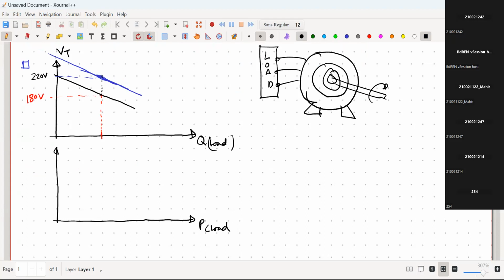Why? If there is a real load connected with the generator, there will be current flowing through it, and this current will produce an RMF, which will try to oppose the rotation of this rotor. So if I do not increase the diesel supply or the force in the shaft, and this rotor is getting opposing force, eventually the rotor speed will decrease.